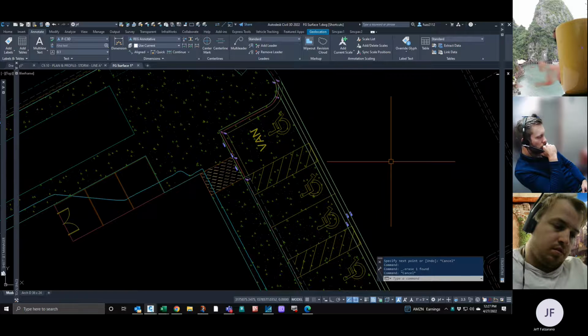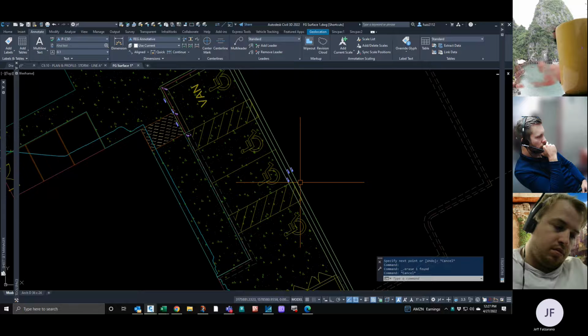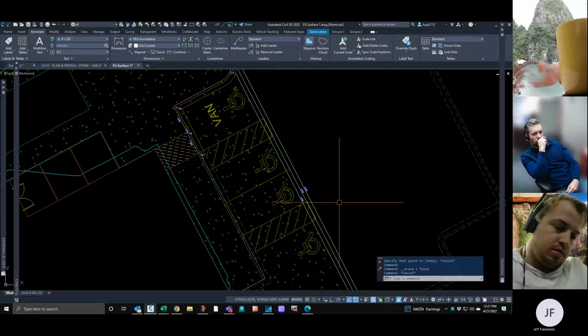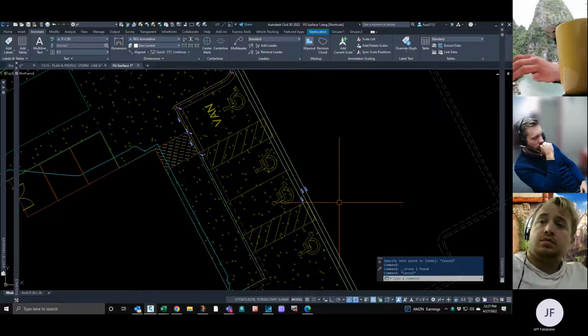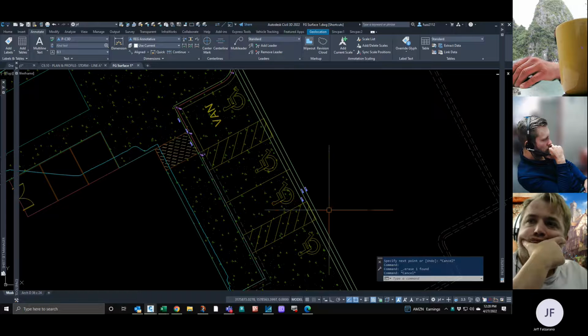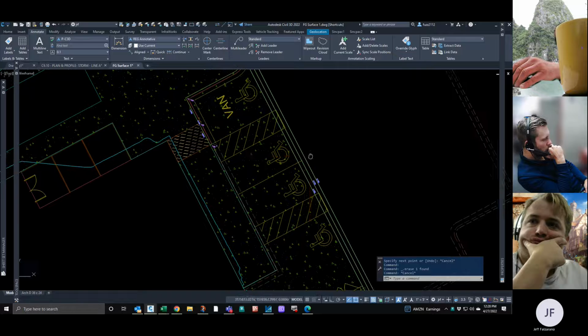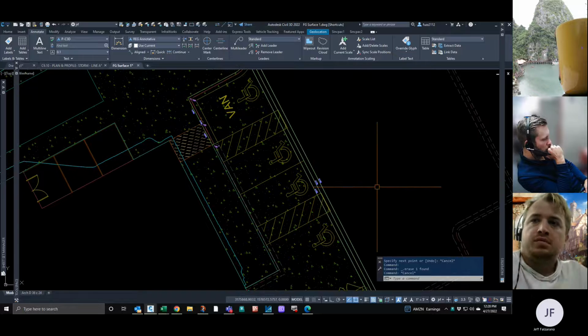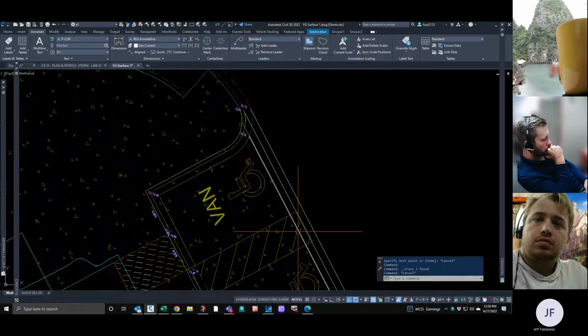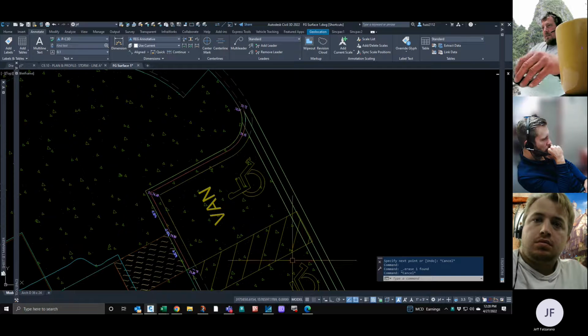So it's probably a little bit flatter most of the time, which is fine, because it'll be a little bit steeper going diagonal, right? Yeah, for sure. And typically, most handicap spaces are concrete, so that's totally buildable. If you do them in asphalt, then you have to make your tolerances a little more forgiving. Can't go more slight. Right.